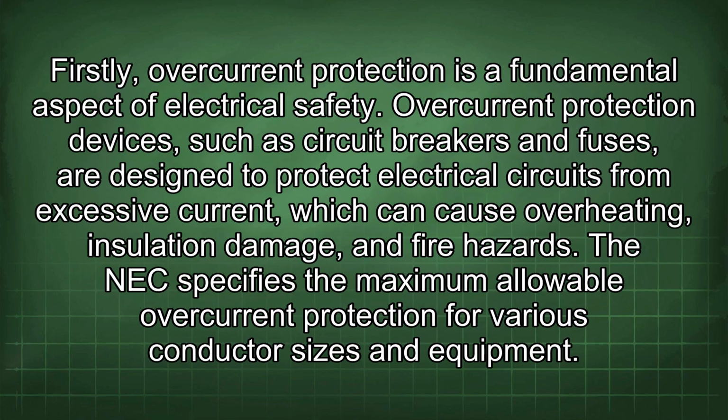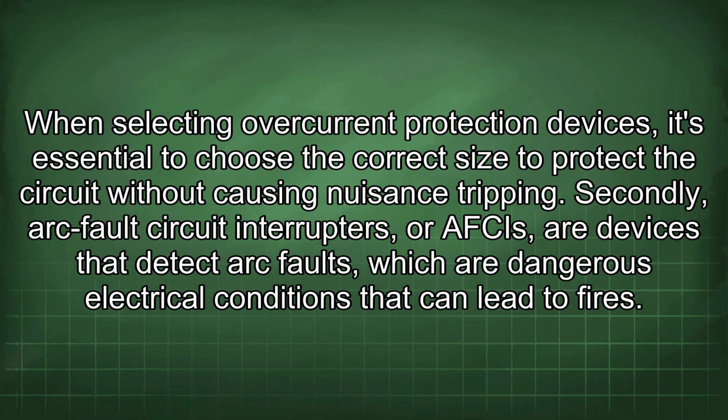Firstly, overcurrent protection is a fundamental aspect of electrical safety. Overcurrent protection devices, such as circuit breakers and fuses, are designed to protect electrical circuits from excessive current, which can cause overheating, insulation damage, and fire hazards. The NEC specifies the maximum allowable overcurrent protection for various conductor sizes and equipment. When selecting overcurrent protection devices, it's essential to choose the correct size to protect the circuit without causing nuisance tripping.